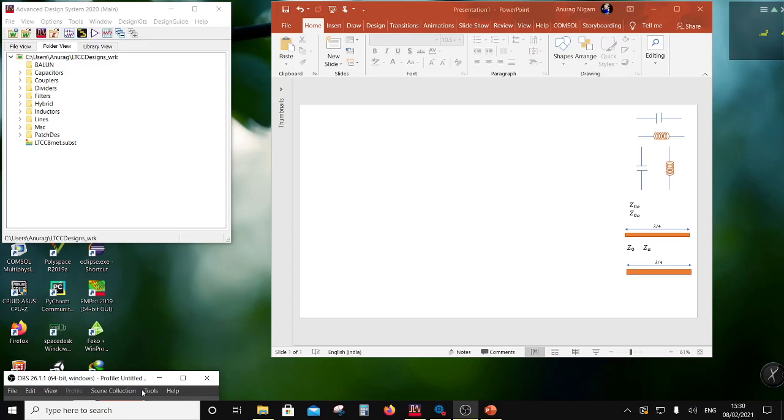The signal which is 180-degree out of phase, for example, a sine wave. So a 180-degree out of phase version of that sine wave would be a differential signal, right? So two sinusoidal signals which are 180-degree out of phase would be called differential signals, right? And a single-ended signal is with respect to the ground. In case of differential lines, the ground basically is the center compared to the two voltages, right? So that's what a differential signal is.